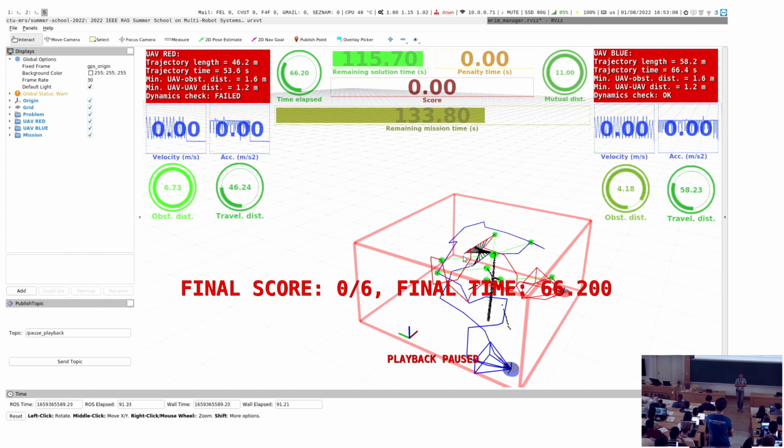I think at one point SpaceX used that on their rockets. And we use it quite happily. It solves the quite complex MPC with 1 to 5 milliseconds of computational time, and it's totally usable. However, nowadays, I would not recommend it. I would probably go for something like Acado or CasADi, which can totally generate quite nice code. Our MPC is linear, so convex optimization, fast, so that's an easy problem. But yeah. Thank you.